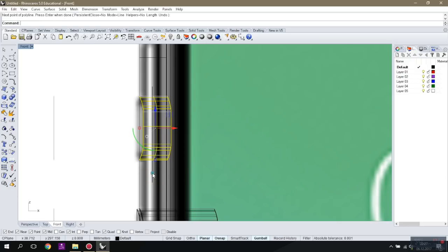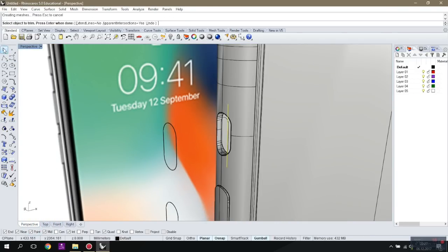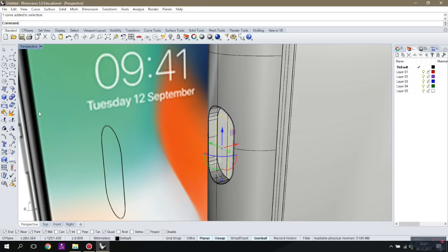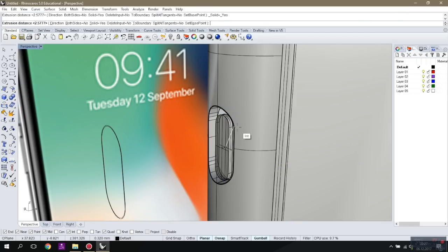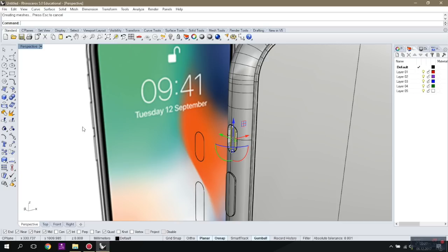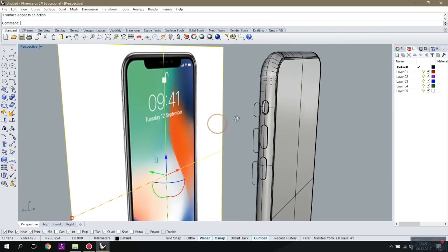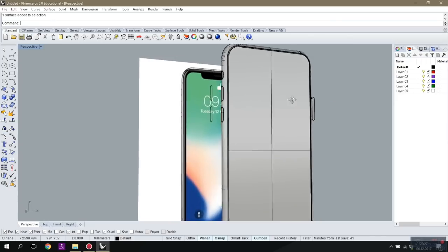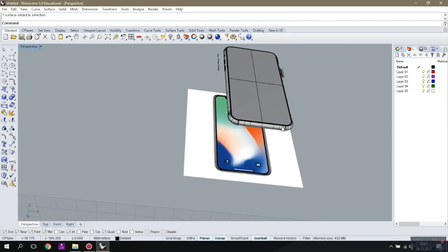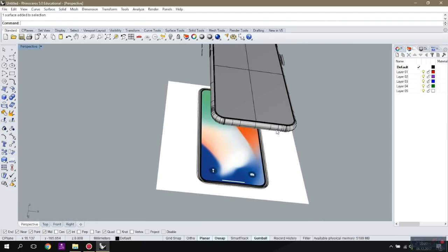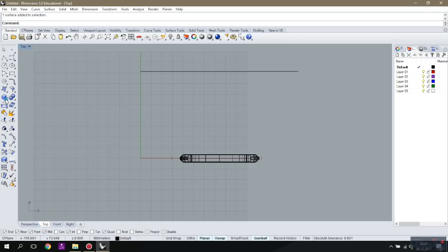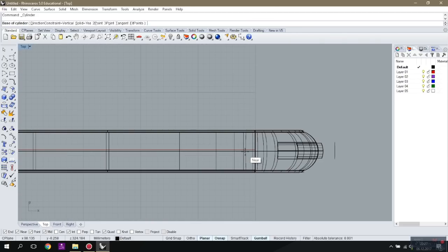so I'm going to cut that like that, and then I'm going to get this button extruded, and maybe I will, yeah, it's kind of alright. Okay, so basically now I need to cut, I guess the iPhone has a couple of holes in there, so I can go from the top view and make some cylinders and duplicate them in a pattern like that, and then just